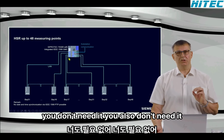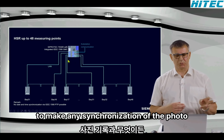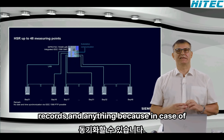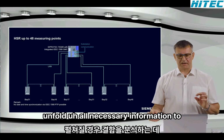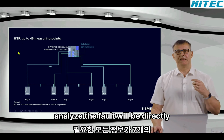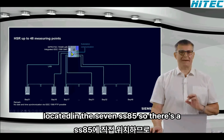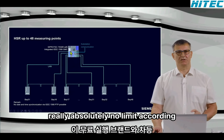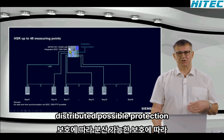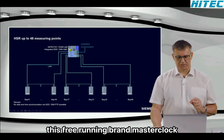You also don't need it to make any synchronization of the fault records, because in case of a fault, all necessary information to analyze the fault will be directly located in the 7SS85. So there's really absolutely no limit regarding distributed busbar protection, regarding differential protection, with this free running grand master clock.